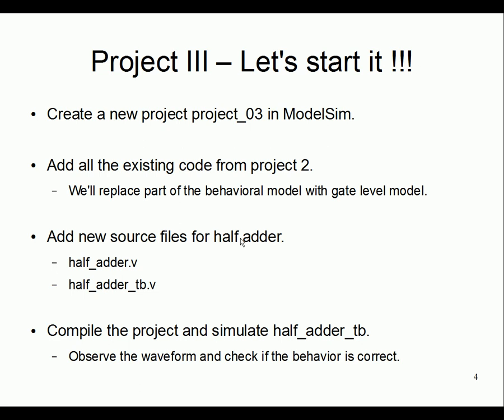So that's why we called it DaVinci 1.0 M, because it is not going to be pure gate level, because the controller unit just goes with the behavioral modeling. It would be similar to project 2, but probably you need to add some more control because we will be dealing with multiplexers and stuff like that. Those control signals will come along with the control signals of your memory, register file, and ALU. Those things will be there like project 2, and additionally there will be other control signals for the multiplexer choice.